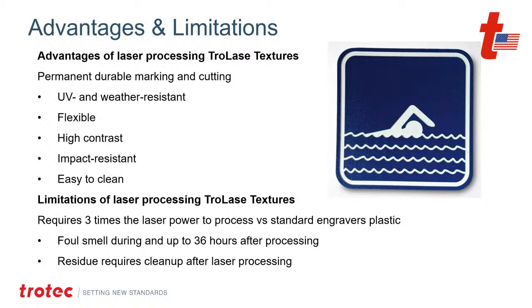Advantages, as I mentioned earlier: UV, weather resistant, flexible, high contrast, impact resistance, and easy to clean, because it does have a textured surface so that you don't get the reflectivity that you would get on your traditional engraver's plastic. Now, there are some limitations. This material is not your engraver's plastic. It doesn't respond the same way as engraver's plastic. It requires about 3 times the laser power to process versus your standard engraver's plastic.